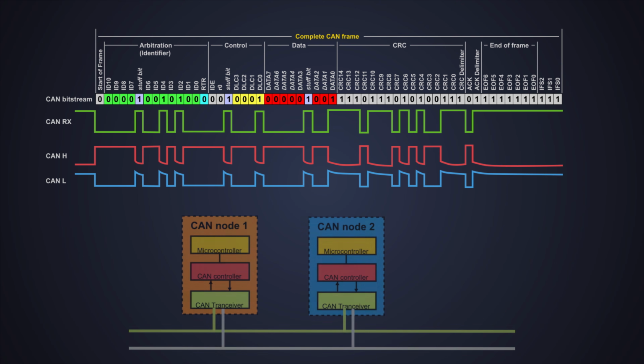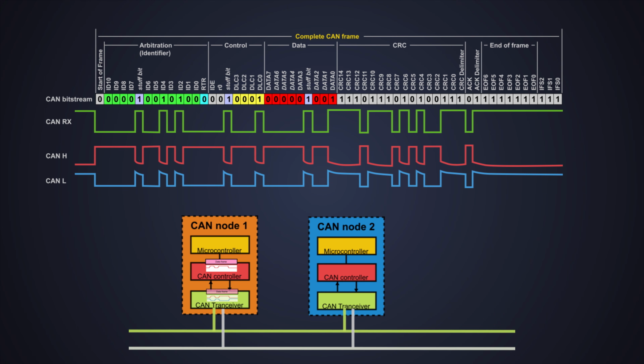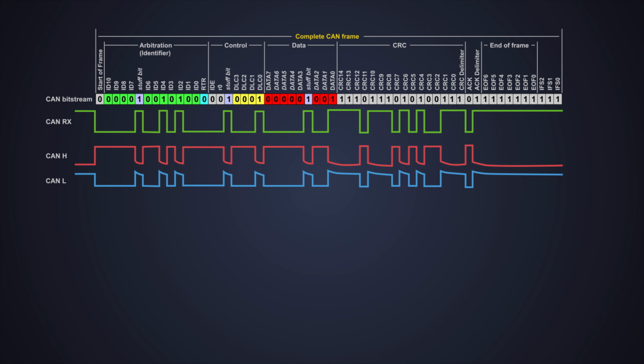And finally, the interframe space is a 7-bit space, indicating the time that the controller has to move the received frame to the message buffer area correctly. It is a time given to the controller to process the packet. If you look closely inside the data frame, we can see the stuff bits also. Well, that's how a whole CAN frame structure looks like.